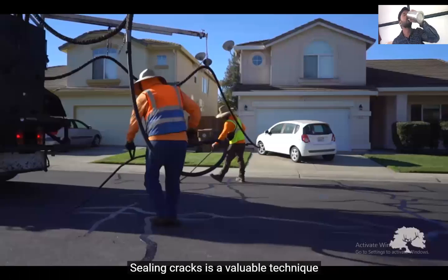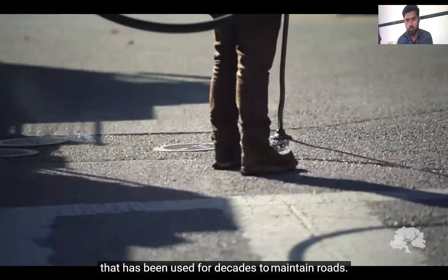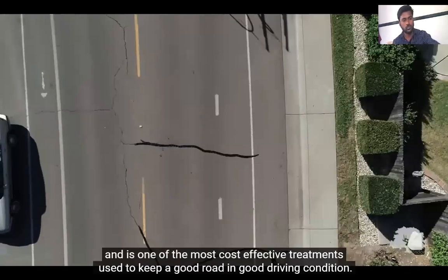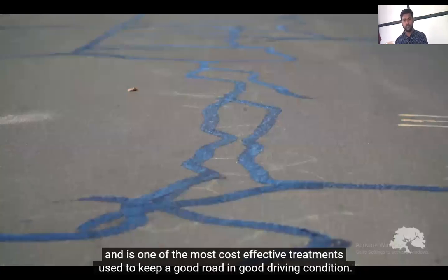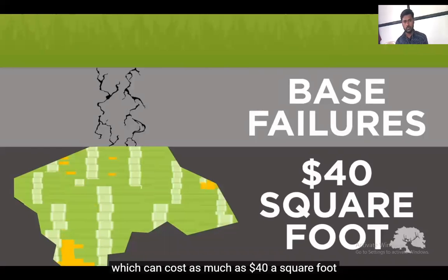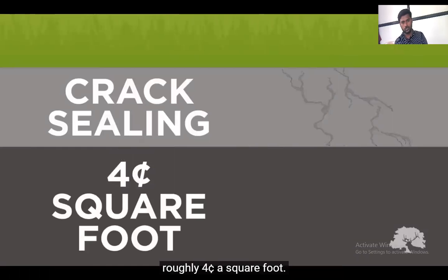Sealing cracks is a valuable technique that has been used for decades to maintain roads. The application can extend the life of pavement up to 7 years and is one of the most cost-effective treatments used to keep a good road in good driving condition. Cracks left untreated lead to costly repairs like base failures, which can cost as much as $40 a square foot, versus crack sealing, which costs significantly less, roughly 4 cents a square foot.